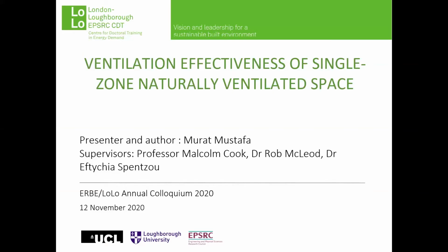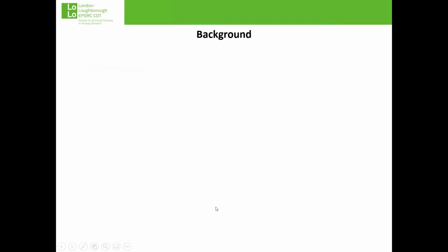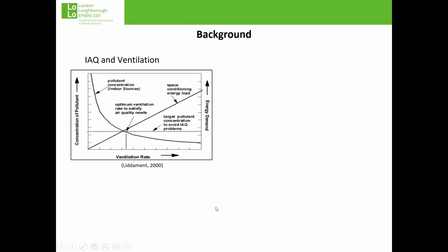Yes, my research topic is local ventilation effectiveness of natural ventilation systems. First, I will start with some high-level background information. In this figure, the relationship between ventilation rate, pollution concentration, and energy demand for mixed ventilation is shown. As it can be seen from the figure, broadly, the energy demand is positively correlated, whilst the pollutant concentration is negatively correlated to ventilation rate.